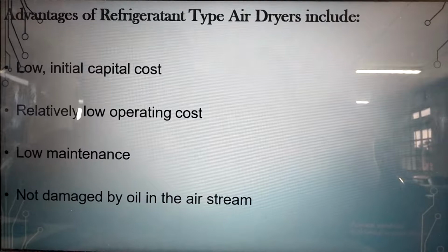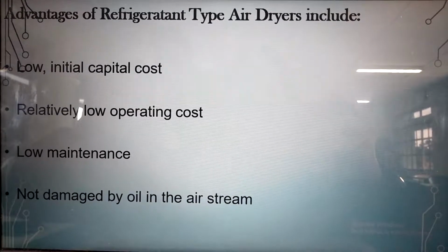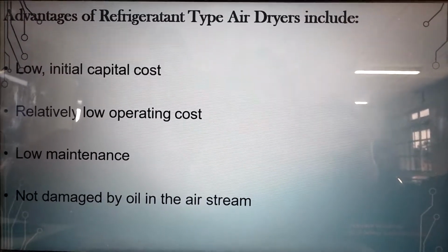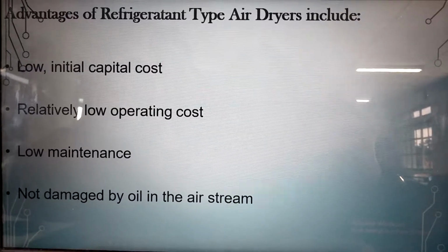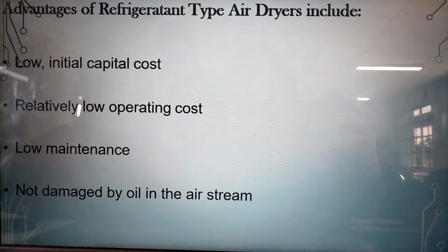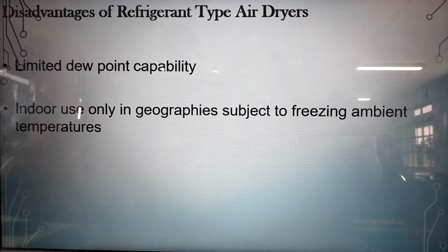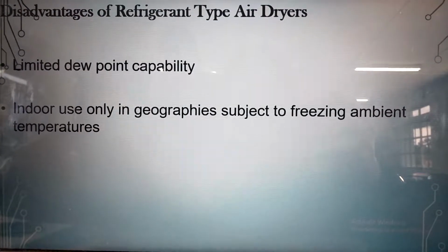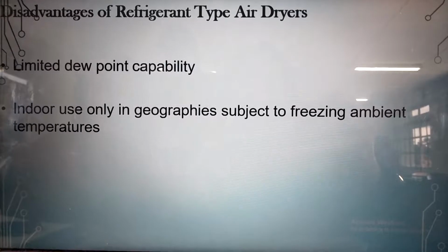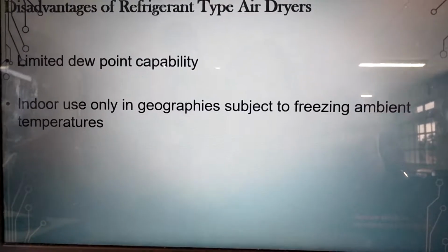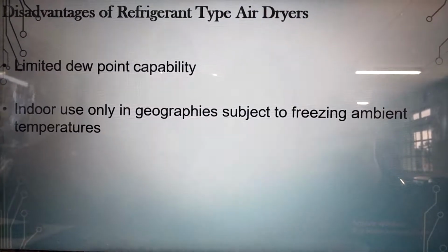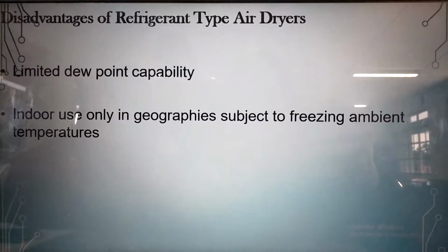Advantages of refrigerant type air dryers include low initial capital cost, relatively low operating cost, low maintenance, and not being damaged by oil in the air stream. Disadvantages of refrigerant type air dryers: limited dew point capability, and indoor use only in geographies subject to freezing ambient temperatures.